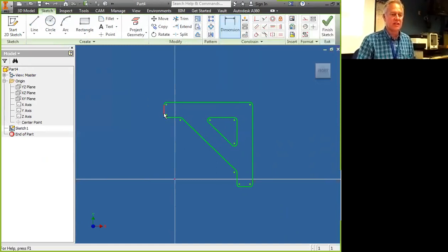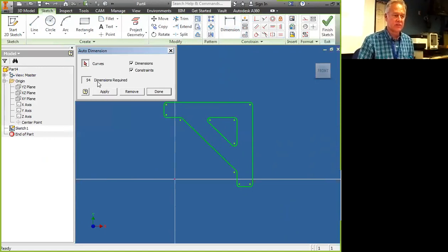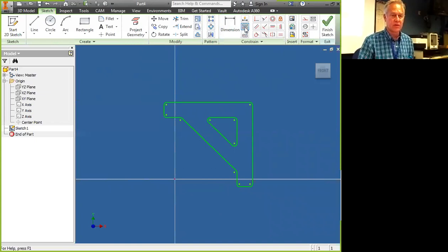A constraint is going to allow you to fixate all the dimensions that we pulled in on this sketch from our drawing in AutoCAD. If I show my constraints, you'll see nothing here that ties this sketch into its relative shape.